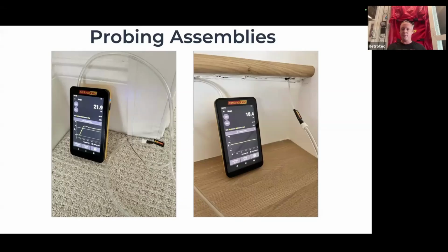But what we found, after getting into the attic and taking a look, is that when we got to the top of the steps, the floor joists ran perpendicular to the steps. So there was an air pathway going from the attic into the staircase. The fix there was to go onto that attic side where that floor joist opened up and just put in blocking and seal it. And we could get there. There was an attic knee wall that we actually sealed up as well.